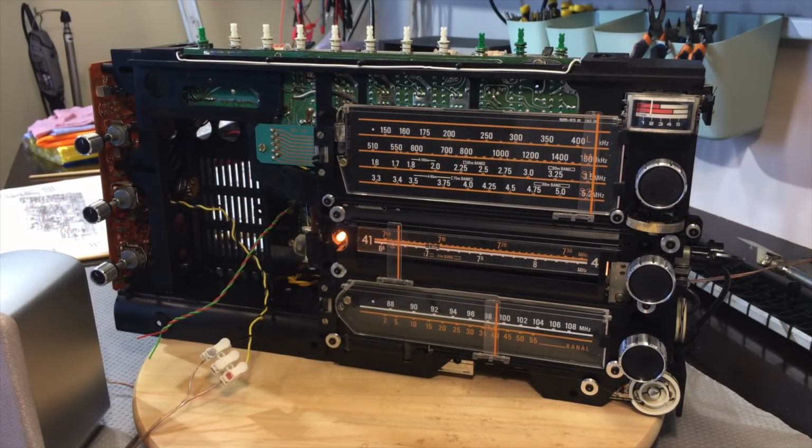Okay. In summary, AM IF alignment is complete. I think there's been a slight improvement. I don't think it was dramatic because when I was speaking this thing, it wasn't. I did make that curve a bit steeper, so maybe it improved selectivity a little bit, maybe sensitivity a bit too. But you know, when you get to that level of detail, I don't think it's made much difference. I think nobody tampered with this before, which means that it had held its values pretty well.